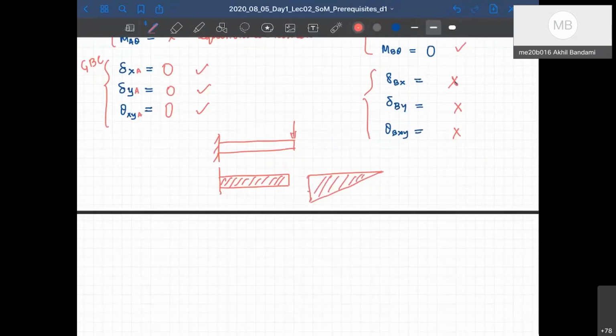So okay. But of course, there'll be an internal force acting on it, sir. Not at that point, just before that point. Yes. At that point, there won't be any force because that will violate the boundary conditions. In fluid mechanics, if you have done, you will see that there are shear forces acting on the boundaries, right? Correct, sir. That will not happen here unless there is a shear force acting on the boundary. If I give a shear force here, then only I will have a force here. Yes, sir. Otherwise, not. Is that all right, Akhil? Yes, sir. Thank you, sir.